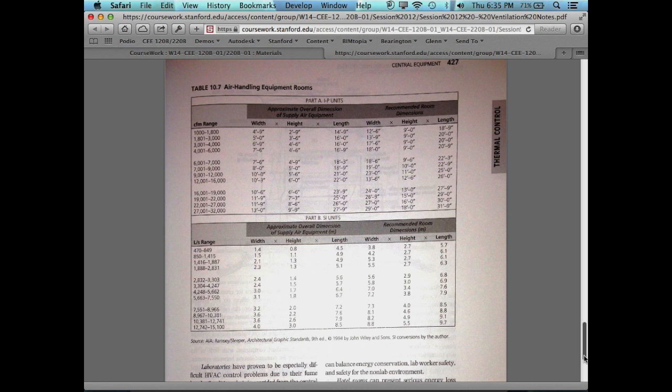Would it disrupt a green roof if an air handler was up there? Like, does it disrupt the air quality that's immediately around? Immediately around it, yes, because it's sort of introducing a lot of hot air or sucking air all the time, either way. If we put it on the roof, we probably want to isolate it a little bit from the area that you're thinking of as your green roof. So you might want to put it behind some sort of screen or just off the beaten track a little bit. Because right around it, all that air is going to be either too hot or too cold. It won't be good for plants. So you do want to separate it a little bit. Kind of baffle it out a little bit.